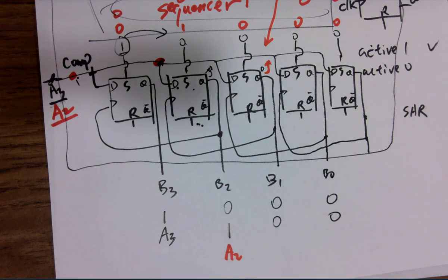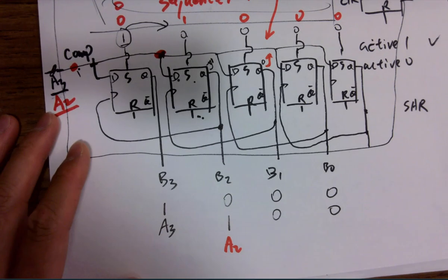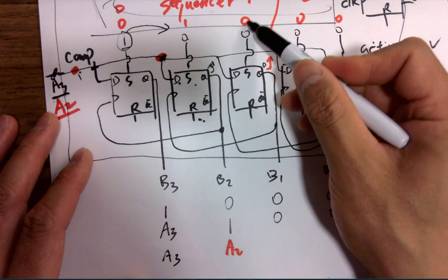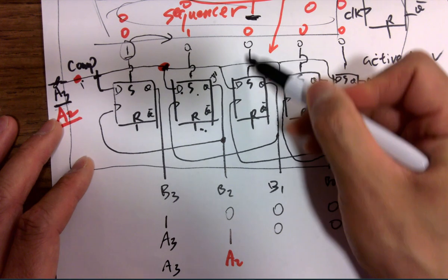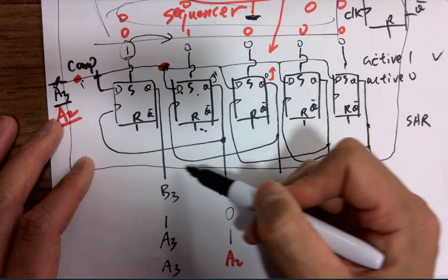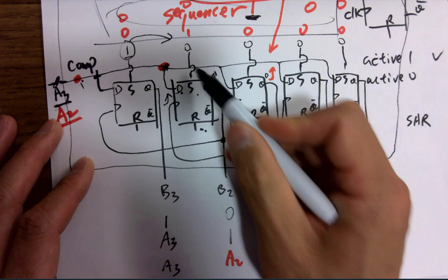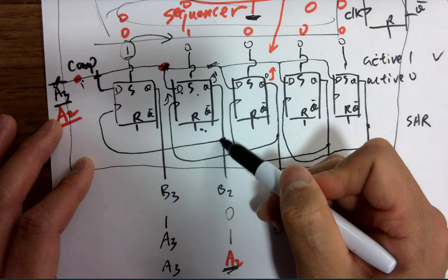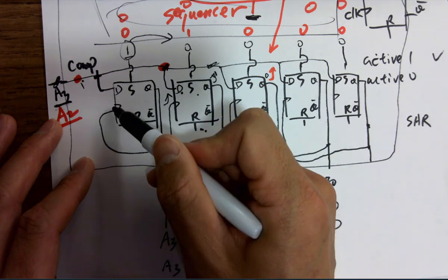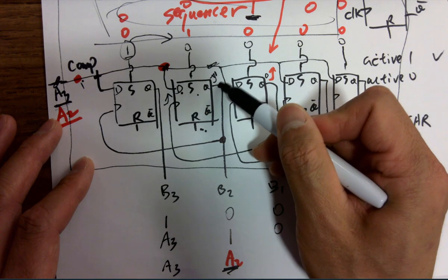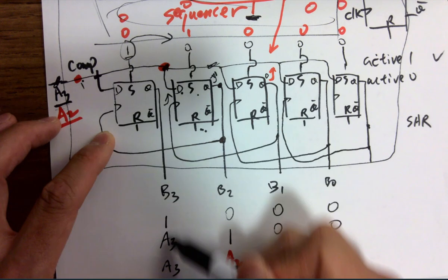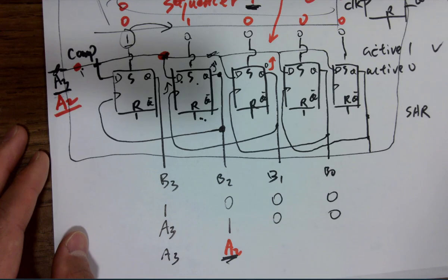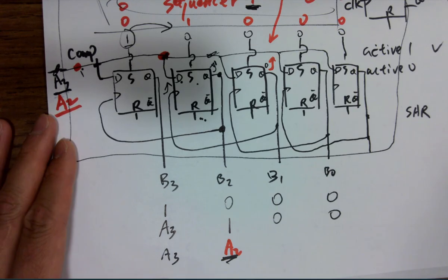What's the case that you're saying? If I'm saying, would A2, can we retain A3 to here or not? Because if this one got a 1 here, and we'll set this guy and get a rising edge here, and we'll register A2 to the Q here, right? And that A2, this output is shorted to the clock of the previous one. Is that possible that we got a rising edge here, so A2 will be registered to the first one as well? Why? Because it either stays a 1, or it's a falling edge and it goes to 0 and it doesn't trigger the clock.